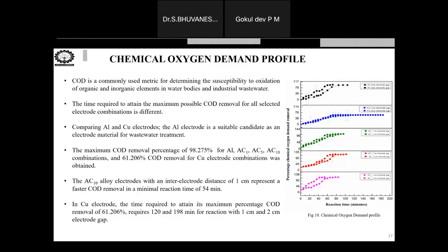When we have taken the pollutants from the water phase, and we are now disposing them in terms of solid waste, that is not good. So he's trying to do zero discharge. Zero discharge means no pollutant should be given to the environment. With that concept, he's saying that the sludge, whatever is left over, the electrocoagulated sludge, we can try to use for some beneficial things like biofertilizer preparation.